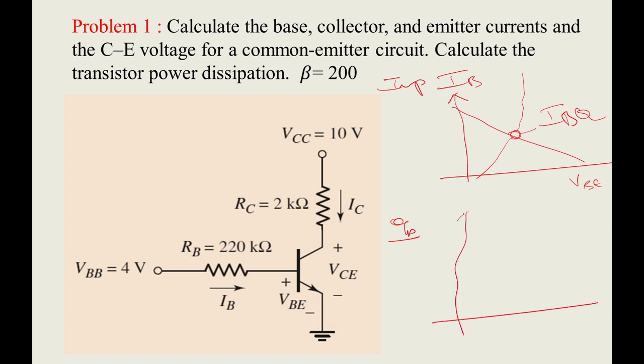Another thing, the output characteristics IC versus VC. See, in most of the problems you will be asked to find only the output characteristics. Input characteristics only for this problem, just to make you understand. Okay, so here also you will find maximum collector current, maximum DC voltage, and you will be drawing the DC load line and you will be fixing the quiescent point. So the quiescent point will be VCQ and ICQ.